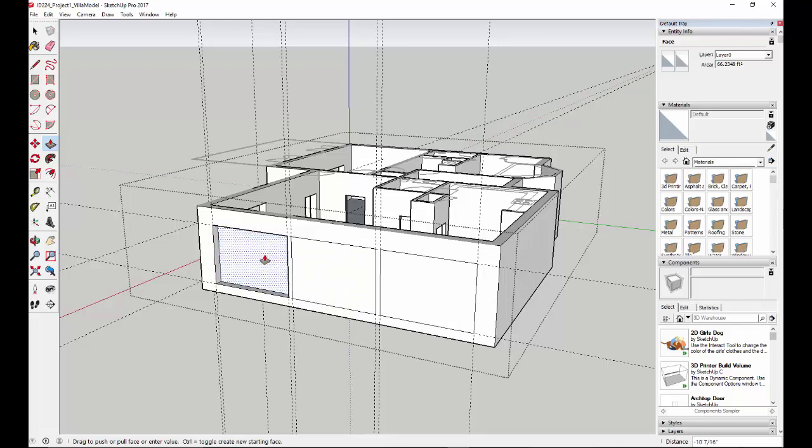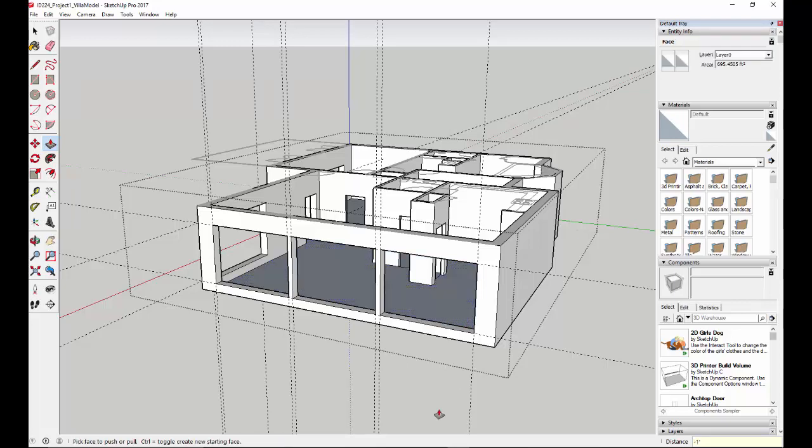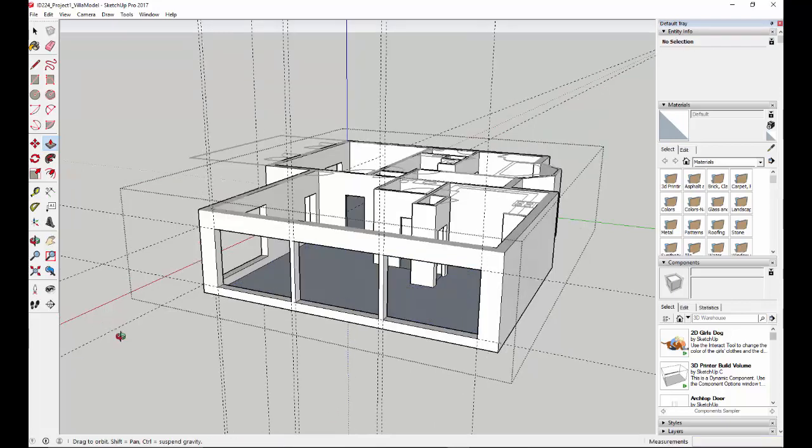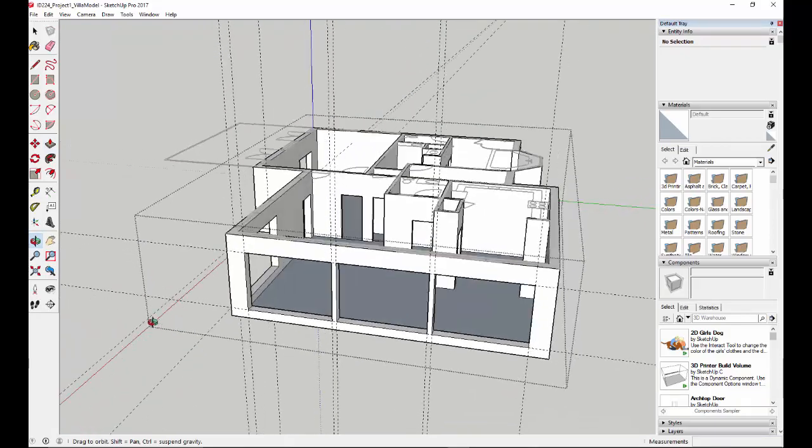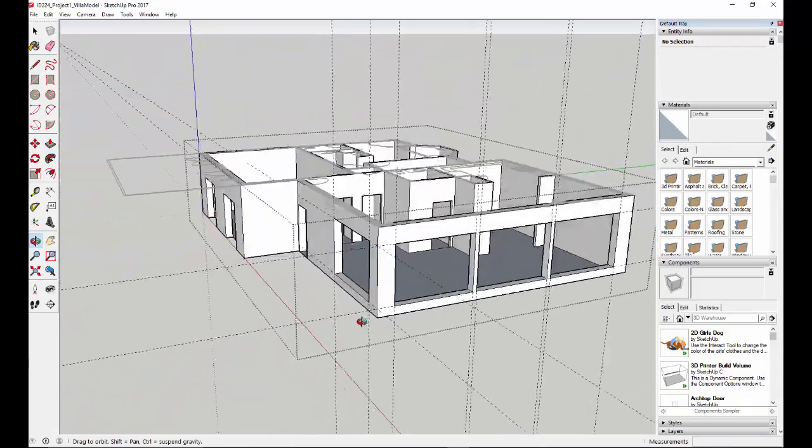And you have to kind of find that one little area, and if you're having a problem doing that, sometimes a good thing to do is as you're pushing and before you let go, just type 1 foot. That's the thickness of that wall. Enter, and it'll automatically do it for you as well. So again, I'm going to push. I'm still holding down my mouse. Type 1 apostrophe for 1 foot and hit enter. Now let go of your mouse and you'll see that it cuts. Kind of a clever little trick, right? So there we got these nice big windows.